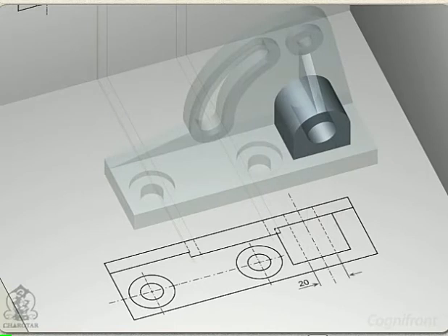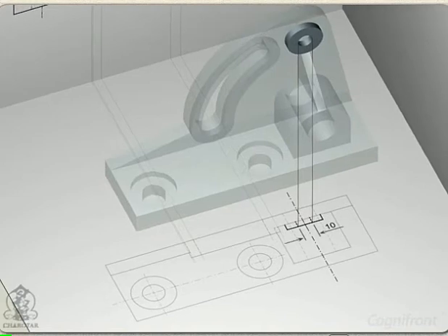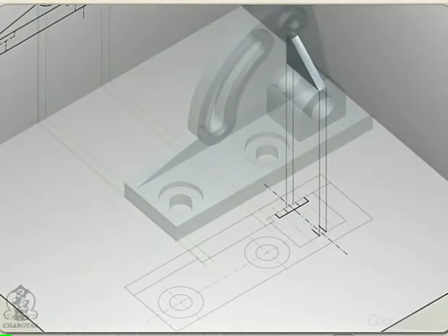hole in it. Observe this acute overlap of the slot with this semi-cylindrical portion as seen in the top view. Then project the boss hole as a rectangle of 25 mm by 5 mm and draw hidden lines for the 10 mm diameter hole in it. Finally draw the projection for the connecting rib.